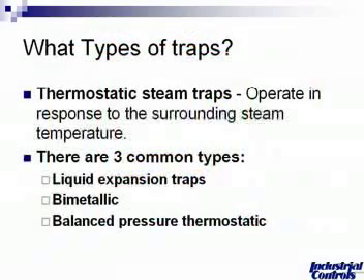What are the types of traps? There are several different styles. One style is a thermostatic steam trap. They operate in response to a surrounding steam temperature. In the thermostatic family, there are three different kinds. There's a liquid expansion trap, a bimetallic style, and a balanced pressure thermostatic.